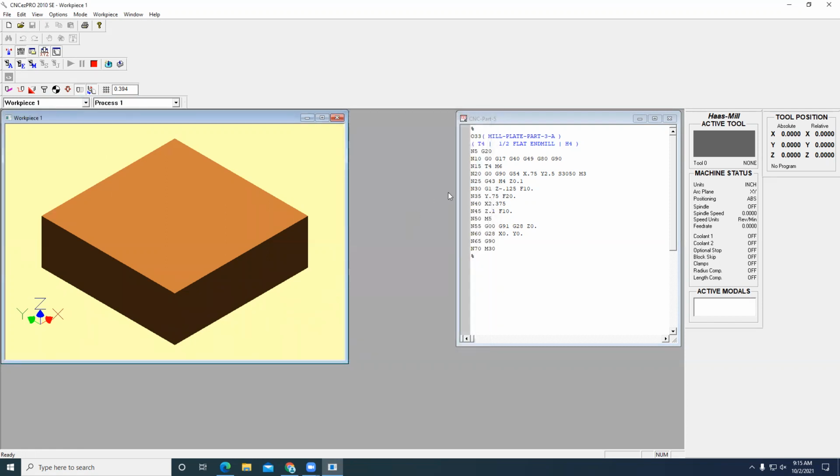The other thing that needs to match is the tooling. The guys that are writing the programs, make sure that you call out which tools are in which current location. So tool number 4, commenting out that that 1/2 inch end mill is extremely helpful. We want to include that information in the programs. Everything else is pretty much boilerplate.